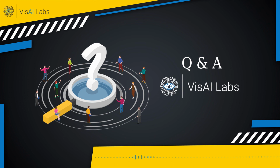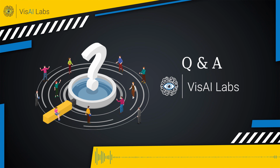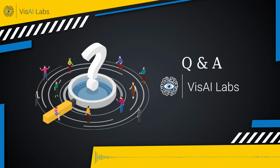The first question is, they want to interface two high resolution global shutter cameras. Is it possible, and how do we do this? Yeah, it is possible. It depends on the host processor we are going to use. If you are going to use a PC, then we can use the global shutter camera. For example, we have C3 Cam 20 CUG or C3 Cam 24 CUG. These are global shutter cameras. Both are full HD, one is color and the other one is monochrome. So you can use USB cameras connected to the PC over the USB 3.0 or 2.0 interface.